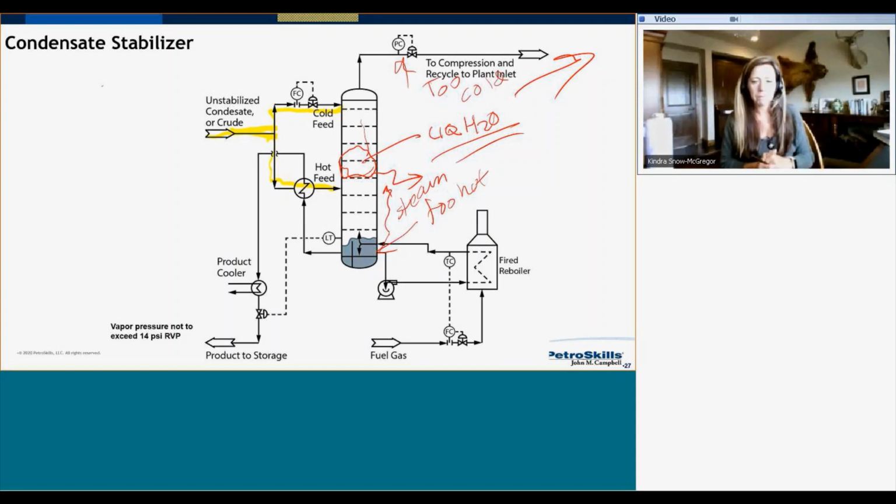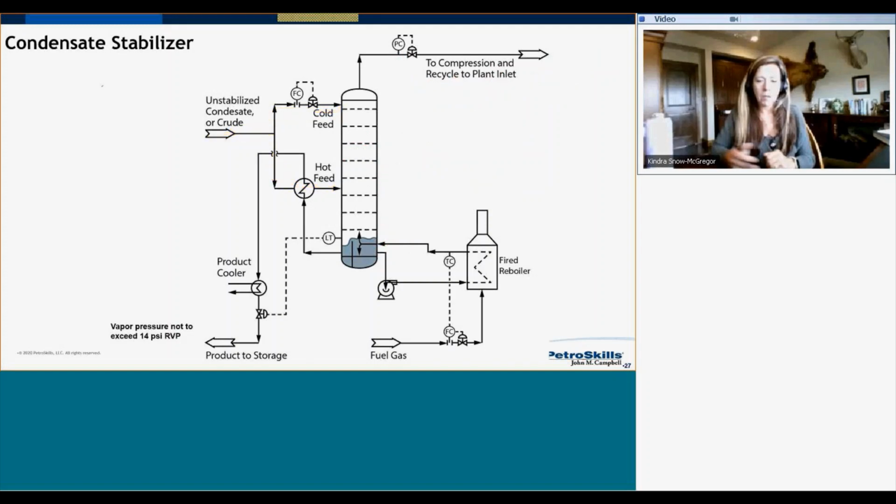Okay, and then the next part of that question is also, could you describe the effect of intermittent or continuous internal reflux on the smoothness of column temperature profile? And this is related to condensate stabilizer as it is defined by the efficiency of interstage/final cooler of overhead compressor.